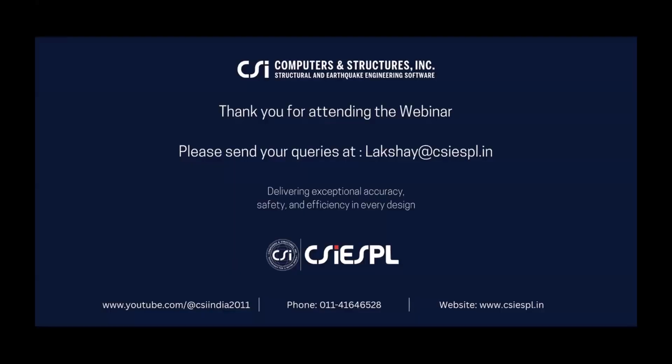So how is the response spectrum converted into user load? Yeah, this is commonly done for many applications. For example, foundation transfer. This response spectrum case is run, and then you get the story shears from the table output. From the story shears, you can get the differences between consecutive stories. That will be the story force, which you can easily get with the help of Excel from the table output.